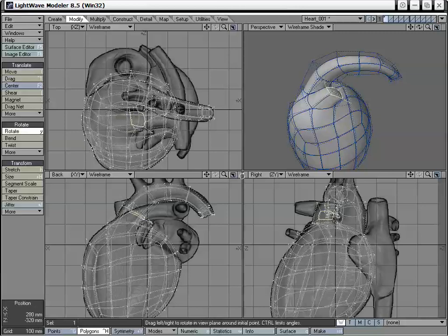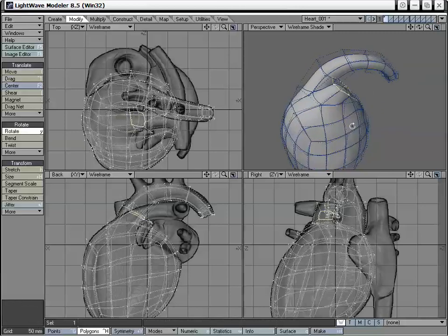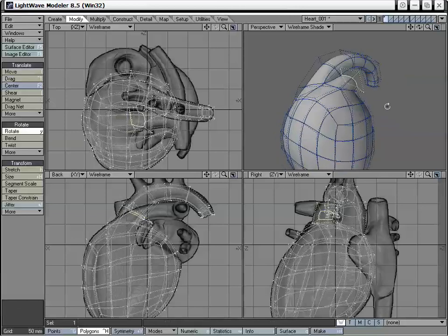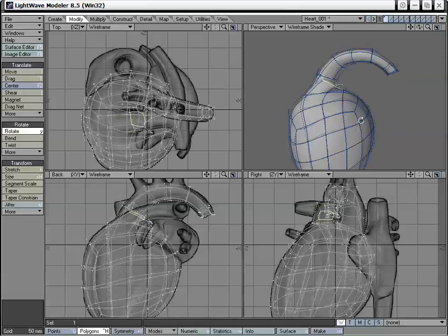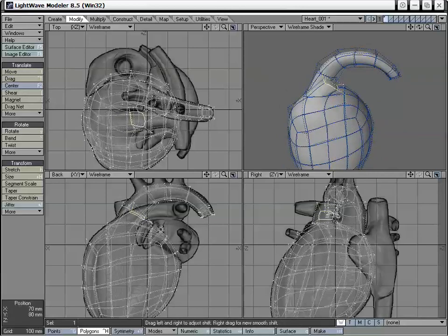And also using all of our viewports as a judge to see where our polygons should be going. Okay, Shift F again, right mouse click, and just doing the same thing we did before, stretching and rotating and moving this stuff into position, all these polygons, making sure it's correct to the image.